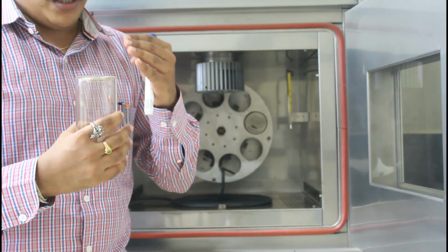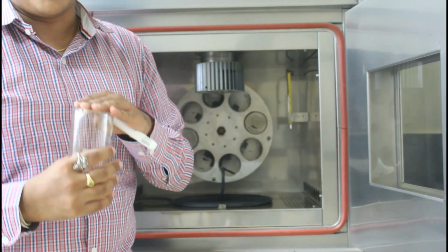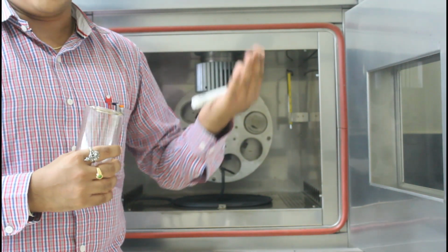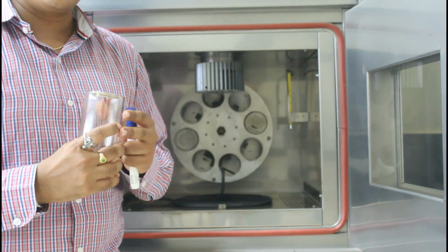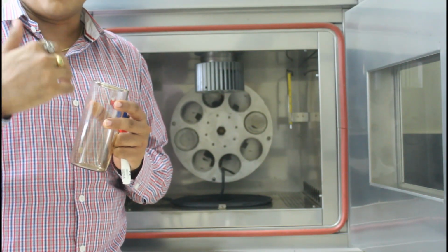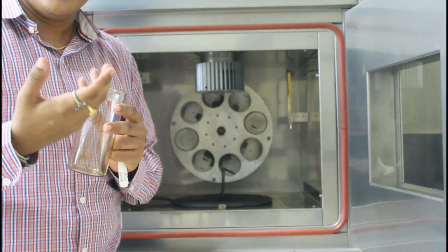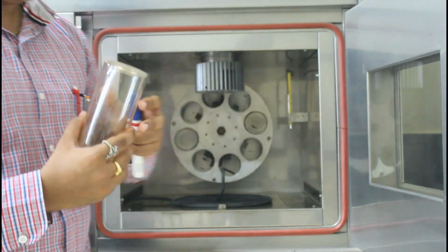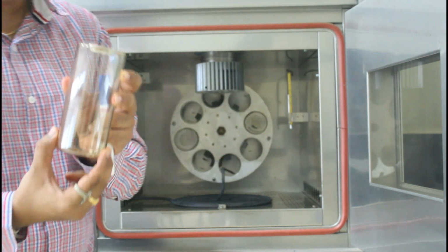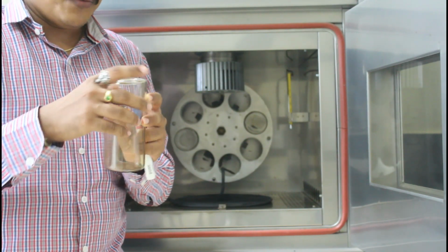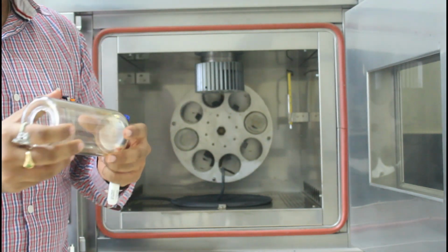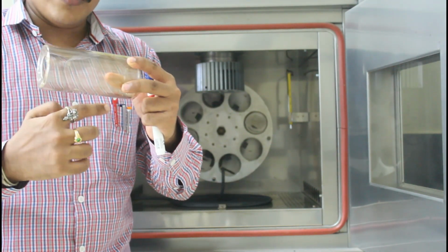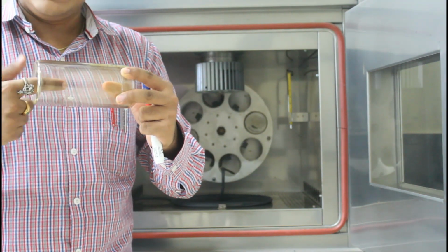Like before aging, let's say you put some mass in this particular RTFO bottle, and after aging, what is the mass? So this will indicate what amount of loss of components happens when the bitumen is subjected to a high temperature. So usually you will put 35 grams in these RTFO bottles, and once you put it, you will roll it so that it will form a uniform thin coating on the inner surface.